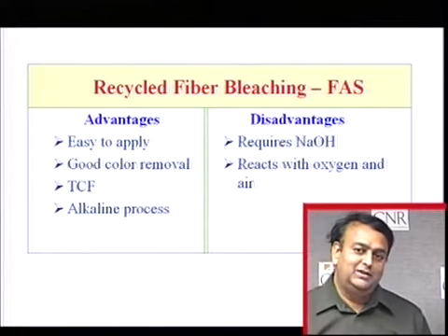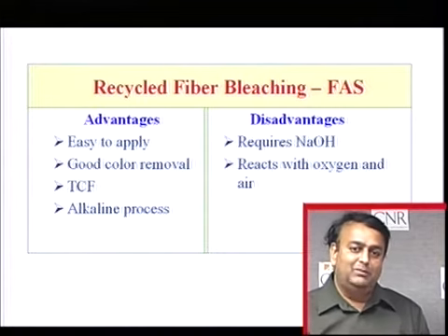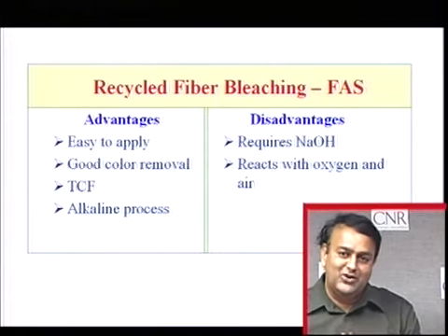The peroxide bleaching in your process starts with pH 10. After the bleaching, the pH goes down to 9. Now, if you want to follow that with a reductive bleaching step, here is the peroxide oxidative bleaching and next is reductive bleaching. So pH goes from 10 to 9. Now, that's an ideal starting point for FAS bleaching. So at 9 you can add your FAS chemical without changing your water loops. So it's a natural flow of the pH.